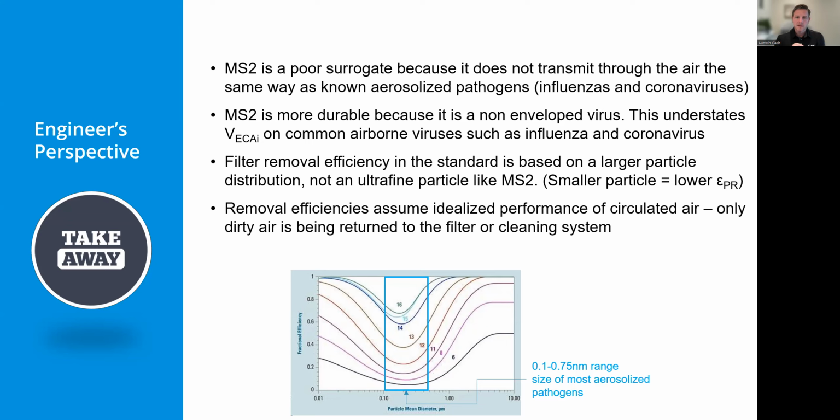The one thing we've learned is that you need to address the problem in the breathing zone. So as close as you can get to where the people are, the more effective you will be as an air cleaner or as a technology. Again, I bring this up because if you've done a clean room design, you look at 15, 20, 30 air changes per hour. A good classroom design getting 6 air changes per hour, you still have a lot of small particles and these viruses entrained in the air that do not move back very effectively. So again, as you just think about from a design perspective, whether a remote filter is a solid choice, that's something we would like to see the standard improve.